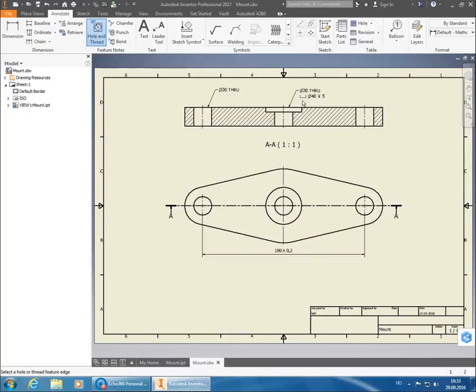That's a counterbore showing with the diameter, and then we have the line with a downward facing arrow on that shows the depth of the counterbore. So this is a way of giving the dimensions of it without actually having to put a lot of dimension lines inside here. So it's a good way of showing everything.